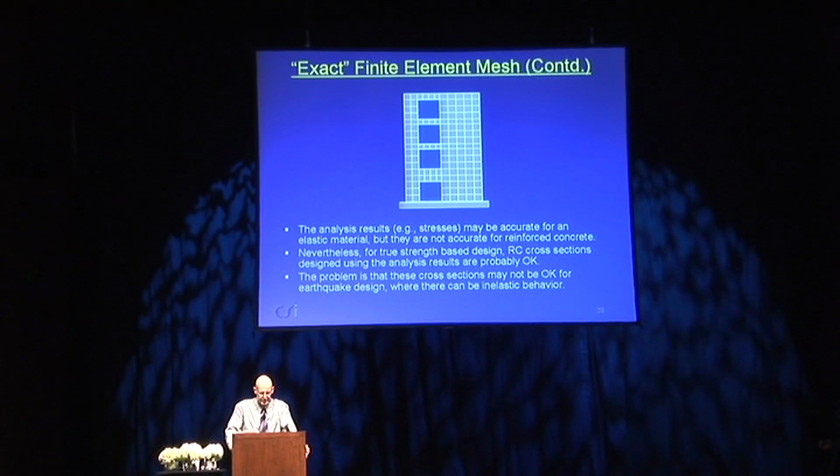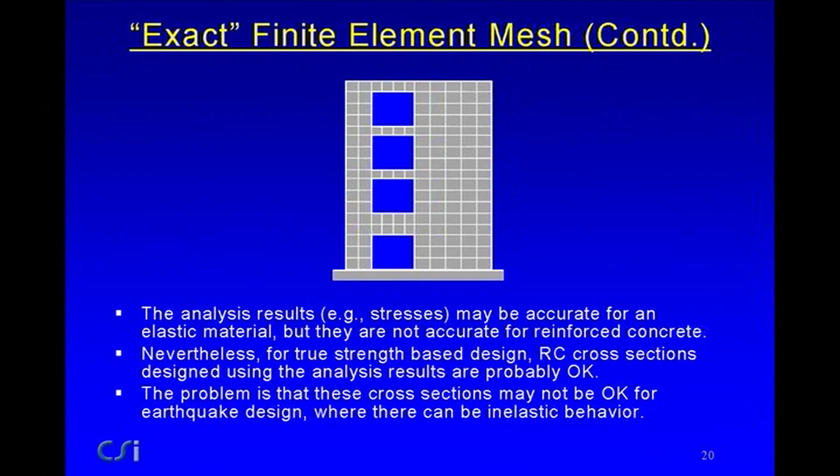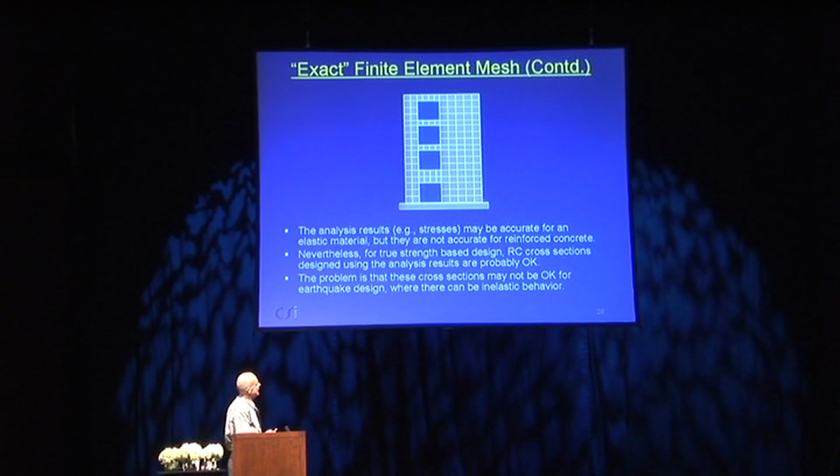But that's not your concern. Your concern is not to get an accurate analysis. Your concern is to get some forces to design the cross-sections. And I want to talk to you here about true strength-based design, where you really are designing for strength, not deformation-based design. The sort of thing you might do, if you want to design this cross-section, is take a cut through here, and from the stresses on those elements, calculate the bending moment and the axial force and the shear force, and then design that cross-section for that bending moment, that axial force, and that shear force.